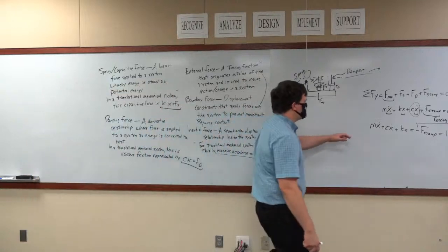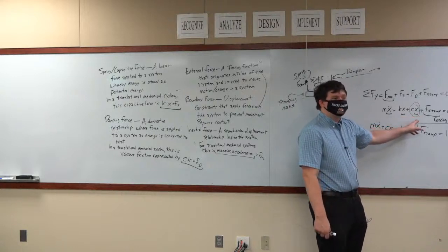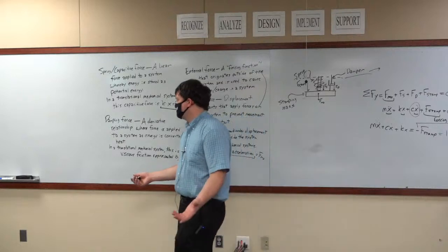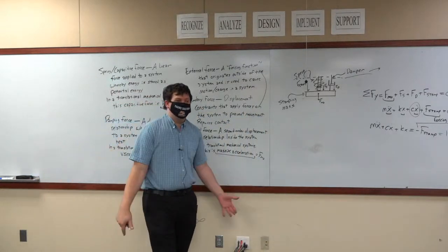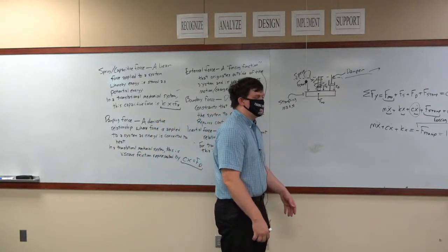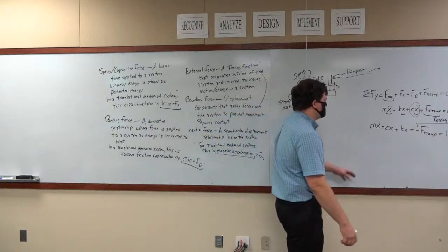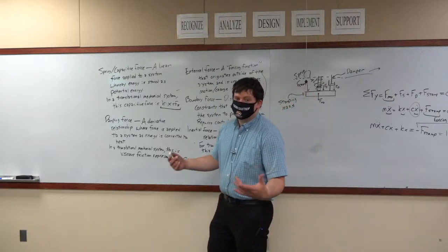This only takes into account the forces from viscous damping, which means fluid friction. It doesn't take into account static friction, it doesn't take into account the dynamic force of friction that's caused by dry contact. This doesn't take into account any of the variances caused by components heating up.